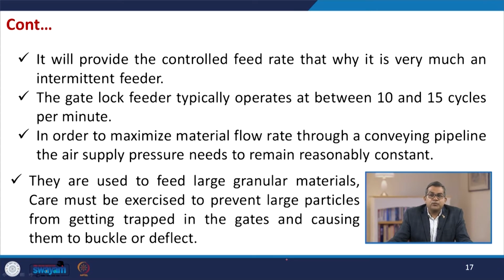They are used to feed large granular materials. Now, while feeding such large granular materials, care must be exercised to prevent the large particles from getting trapped in the gates and causing them to buckle or deflect, because a large particle may block the opening of these gates.